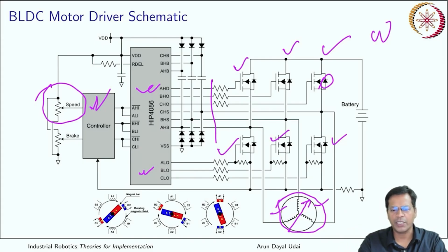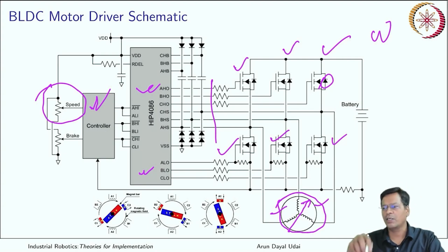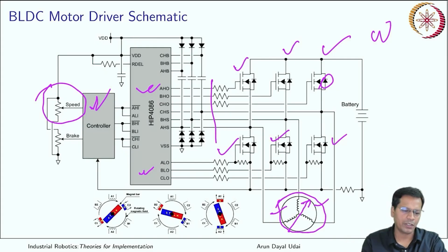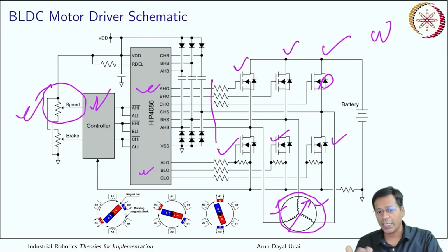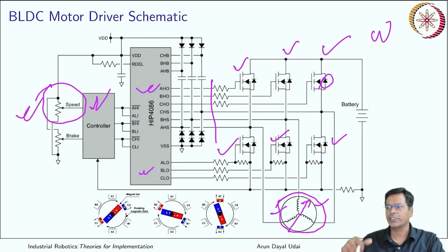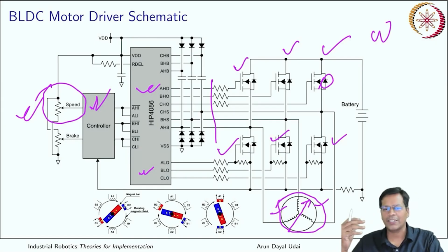So if I say sine omega t plus whatever angle is there, omega is controlled. The rate at which this field rotates depends on this. So speed can be controlled, and you can even make your field go in the counterclockwise direction. If you are moving in the clockwise, you can also go counterclockwise. So both the direction and the speed are easily controlled.